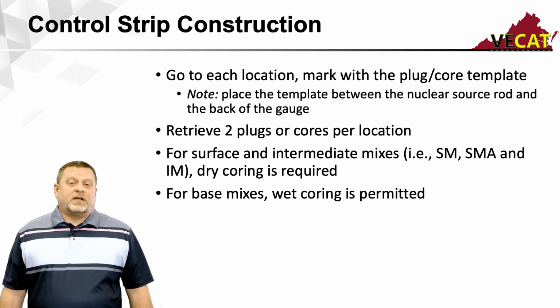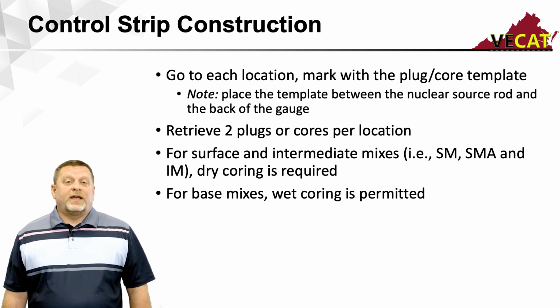We're going to, as I said already, if you're doing plugs, we're going to take 2 plugs or cores per location. We'll show you how that goes going forward. And if we're doing surface or intermediate mix, we're going to dry core. And if we're doing base, we will wet core, just because the pavement's too thick to get a dry core specimen.